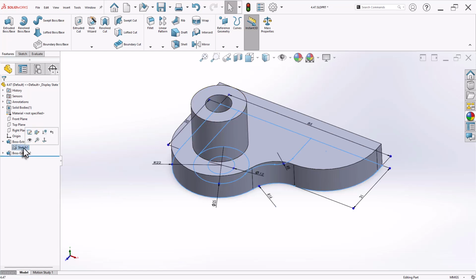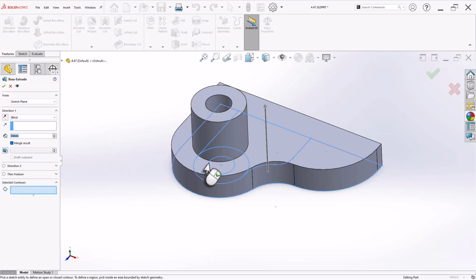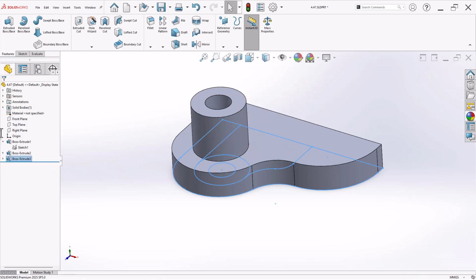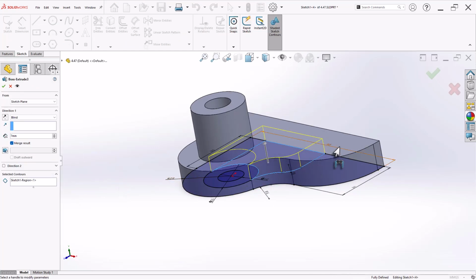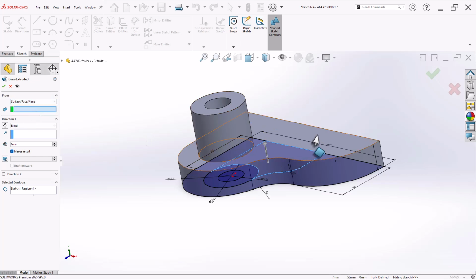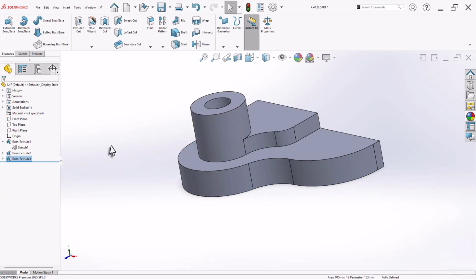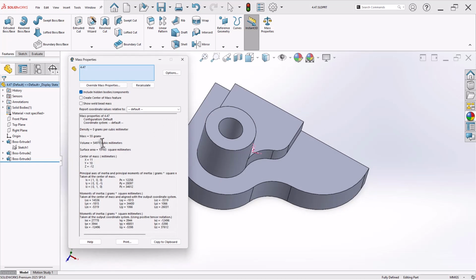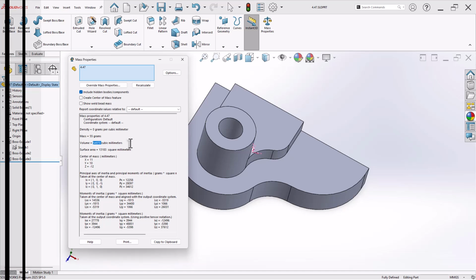on the bottom. Again, let's reuse same sketch and use this region, but the thickness as given is 7. Sorry, that thickness is measured from the top surface. So we need to change the starting locations and it is going to be blind by 7 mm. Now let's measure the volume. So it is 54970, which is completely matched with the solution answer.